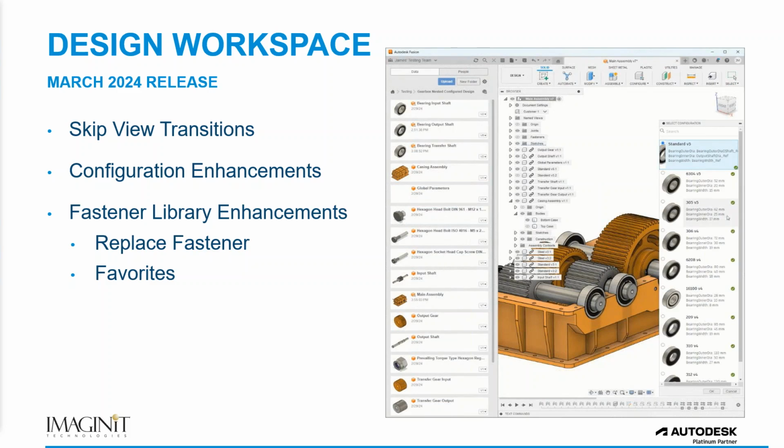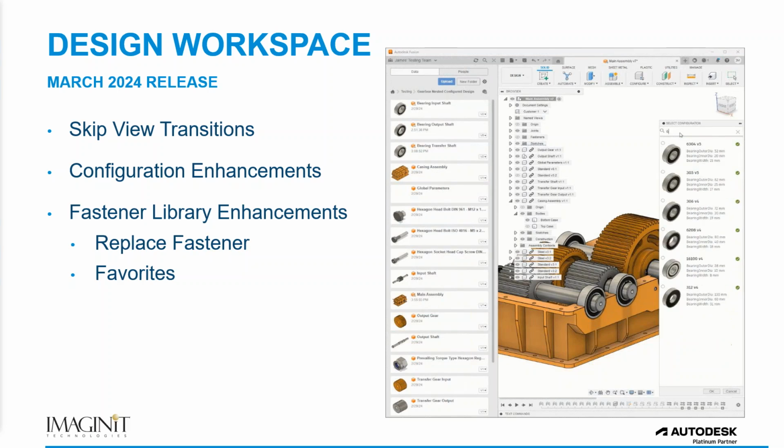Next up, we have some enhancements to configurations. We can now move rows and columns inside the configuration table. And lastly, something of note here is the fastener library has had some major enhancements, including the replace fastener functionality and the inclusion of favorites now. So if you use a consistent set of fasteners, you can add them to your favorites list and keep them on tap. This is really handy because the fastener library is growing quite quickly. There's so many different fasteners in it, it's almost hard to navigate. So favorites makes it really nice if you know you're going to be using a consistent set of fasteners.